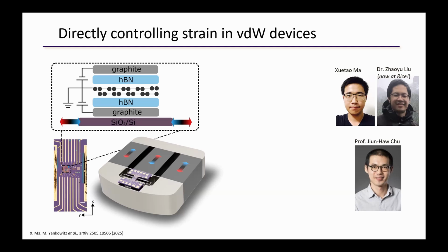So the idea is that you have three piezos that are arranged in this line, and then you epoxy them to titanium sample plates. You apply the same bias to all of the piezos, but you pull the outer two oppositely from the inner one. So say if the outer two expand and the inner one contracts, that will open a gap in the sample stage.